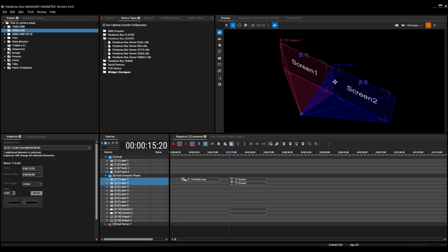And now it comes: 16 units, because Pandoras Box Render Engine always relies on 16 units to fit the first connected monitor device. So mostly the local monitor on the manager, if you use a manager scenario, will set 16 units to the size of the monitor.